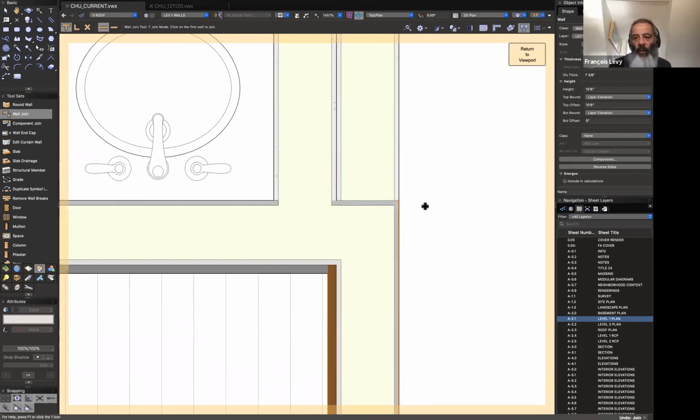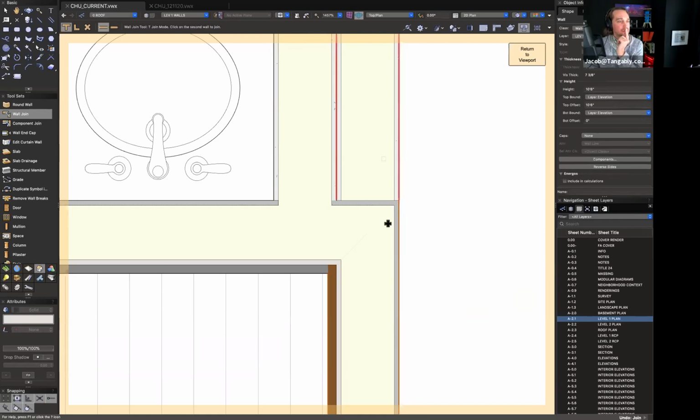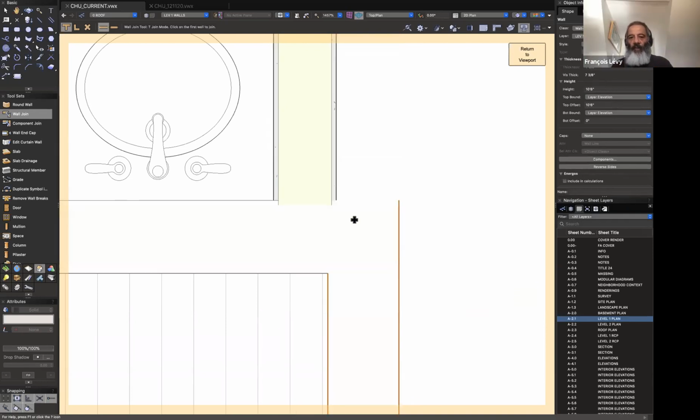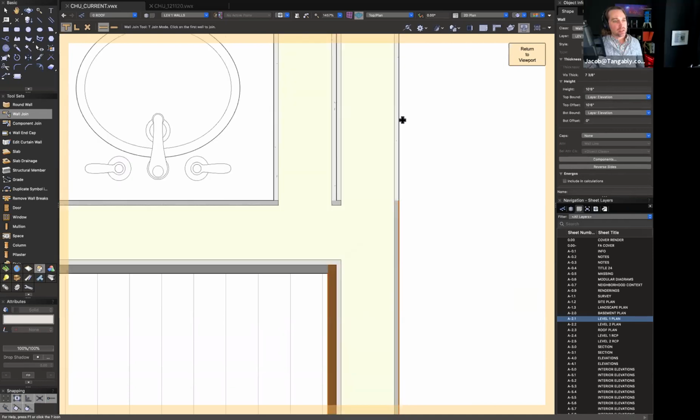The right-hand wall of that double interior wall, you can do a T-join with walls that are parallel, like collinear walls. So you could T-join that to the outside. No, to the wall that's below it, to the other vertical wall. Yeah. Try that. Okay. That also works. Sometimes you've got walls that, for example, if you had a baseboard as part of the wall style, you'd want that to continue.